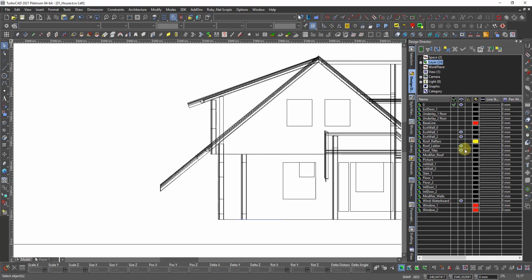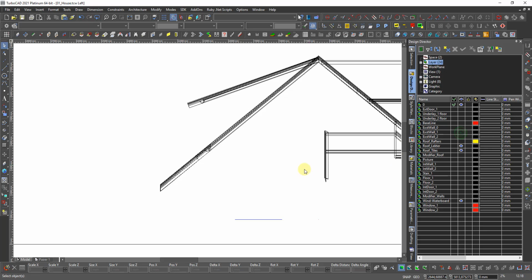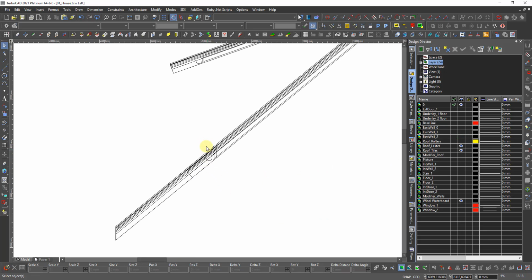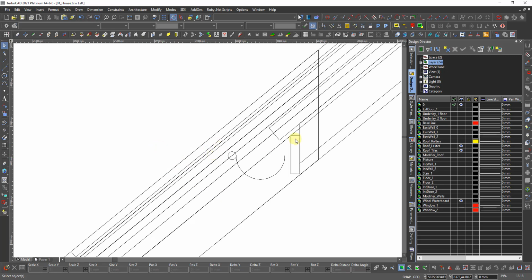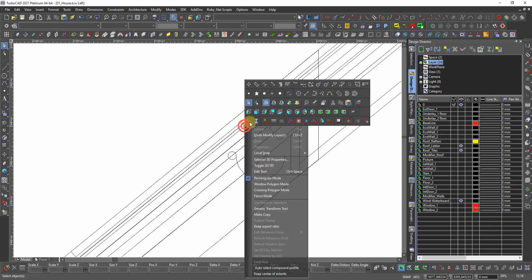So I can take away external walls. And then I wanted to go coming down and cover this one. Go 90 degrees down there. So we can set the work plane by face it. That's not important, we can just set it on the side here. Work plane by entity, no, by active view.